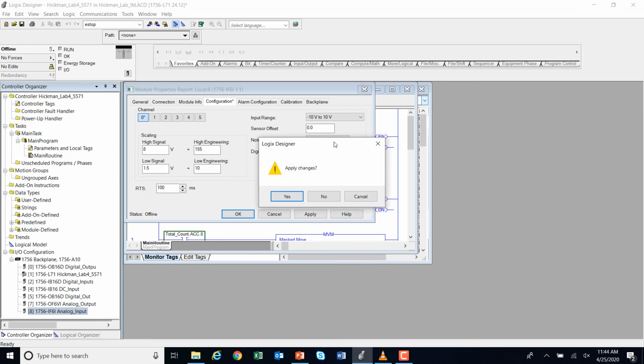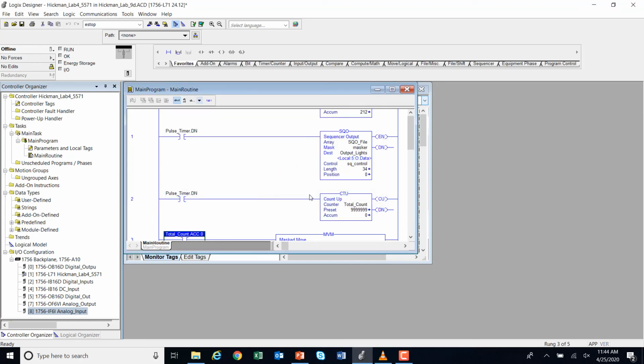And so when you create an add-on instruction, it is going to then populate here under add-ons or my favorites, whatever you call your add-on instruction. I think our one is called F to C here, our first one that will convert Fahrenheit to Celsius. It will populate right here, okay, F to C, and it'll be on my favorites, okay?